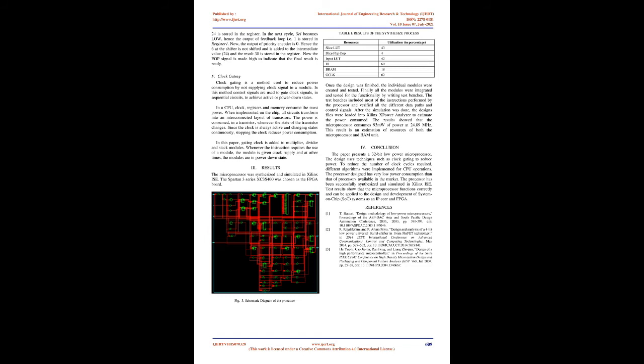In this paper, clock gating is added to multiplier, divider, and stack modules. Whenever the instruction requires the use of a module, the module is given clock supply, and at other times, the modules are in power down state. Results. The microprocessor was synthesized and simulated in Xilinx ISE. The Spartan 3 Series XC3S400 was chosen as the FPGA board.